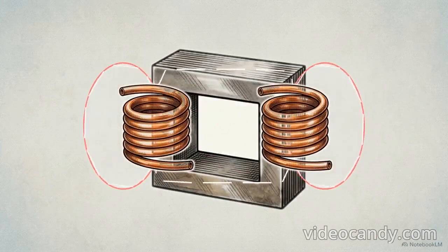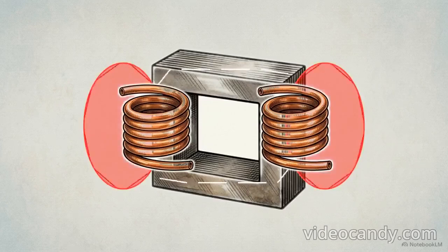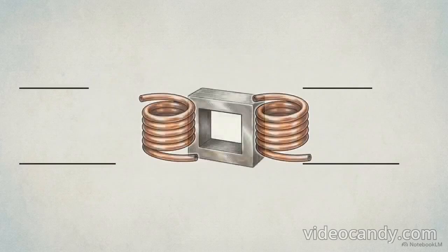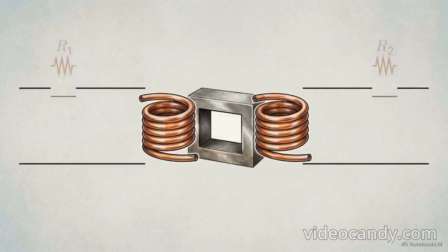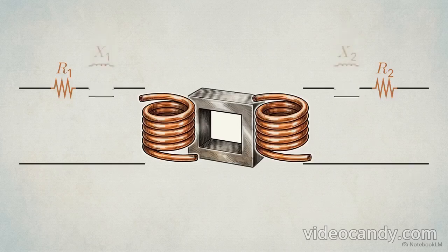Beyond the resistance of the wire, we must account for magnetic leakage. In a physical machine, magnetic fields cannot be perfectly contained within the iron core. Some of the flux breaks away. This escaping leakage flux loops through the air and links only with its own winding. It contributes nothing to energy transfer, but produces a localized, self-induced EMF that chokes the current.